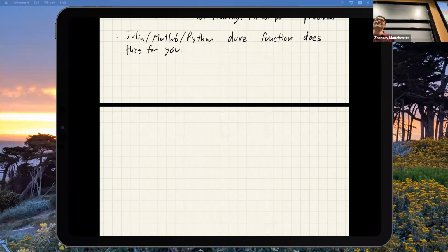It's really, really good. If you're moving its arm, doesn't the A matrix change? Yeah, but you're linearizing about some pose, right? If I have a balancing pose like this, it's the same as the homework 1 quadruped balance. In fact, if you want to try this, try it on the one foot balancing quadruped. You write that down in joint space. Yes, it's moving around, but as long as it doesn't move too far, A is a pretty good approximation. You can really shove the thing and it will do surprisingly well at balancing. It's hard to beat this.